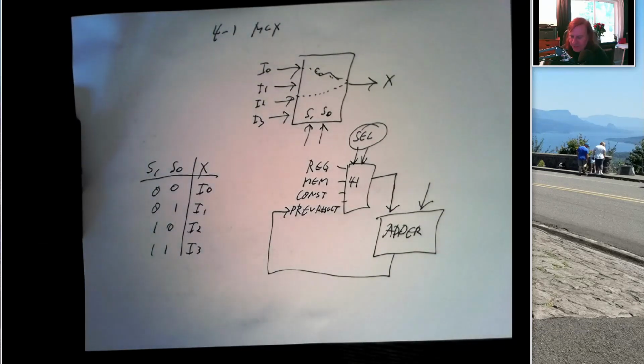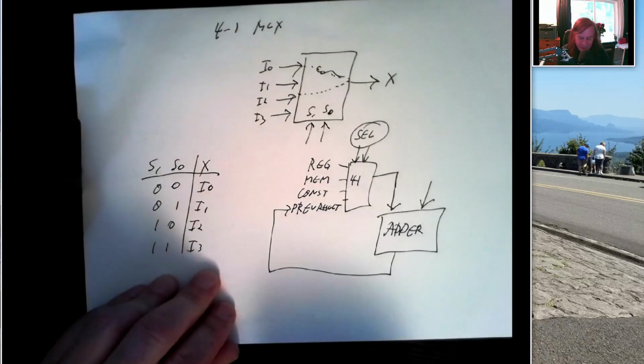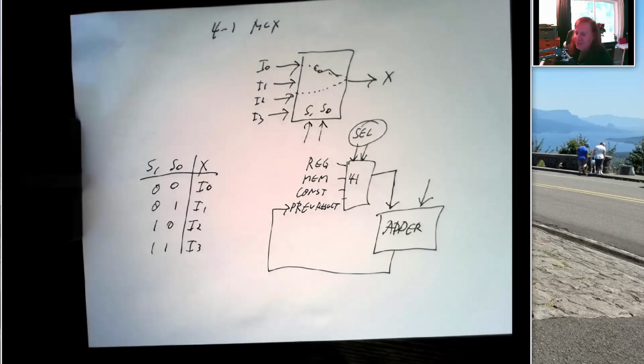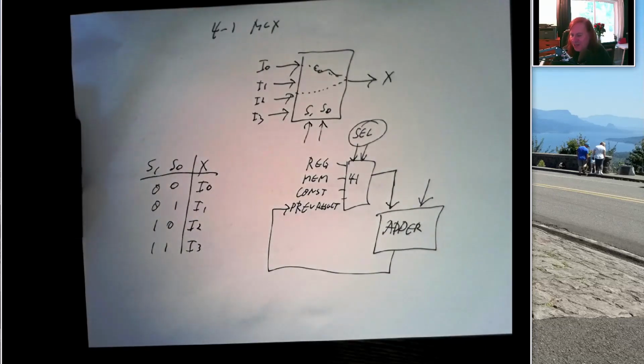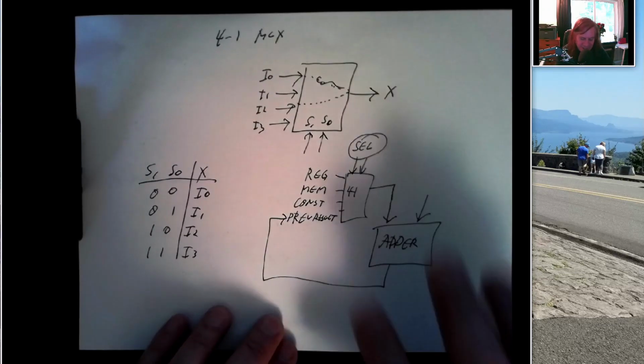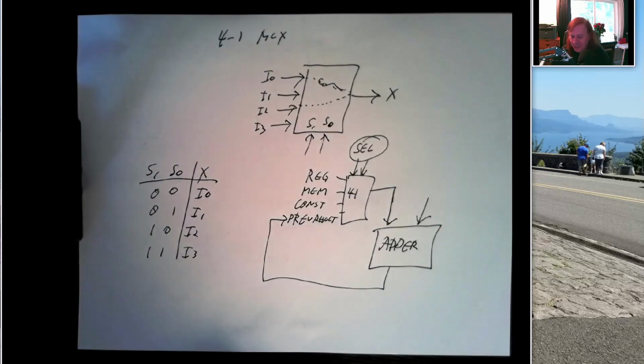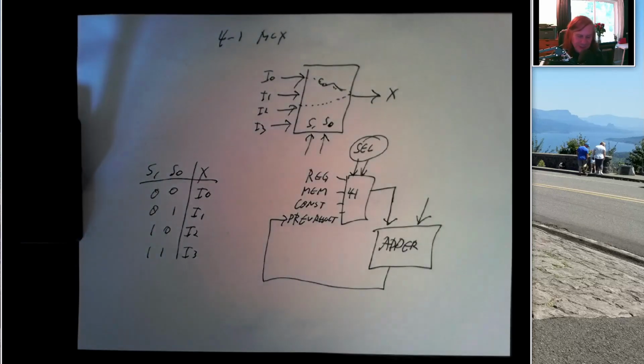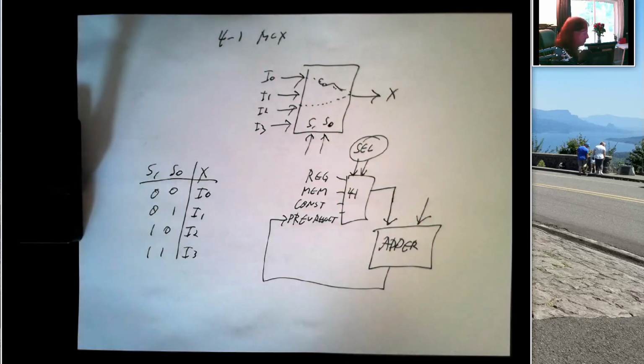And this is how we program what happens inside a CPU, the sort of microarchitecture of a CPU, by basically controlling how things move around in the CPU from input to output. So Engineering 270, we may dig into this a little deeper. We'll look at what's called the data path inside some CPUs and see arrays of multiplexers moving data around. So that's one thing that multiplexers are good for.